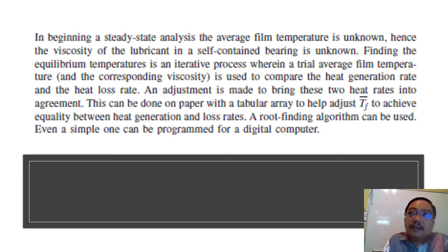You want to find a suitable temperature, and it is an iterative process, meaning many trials and errors, using your experience also. In practice you should ask your senior technician or senior engineer what the temperature is. If your product is a new product, then you have to do trial and error many times, until you get the suitable temperature for your inlet lubricant. Because along the process the temperature will rise, and then the viscosity of the liquid may become lower gradually over time. So what is the suitable viscosity for that lubricant? It is a trial process.